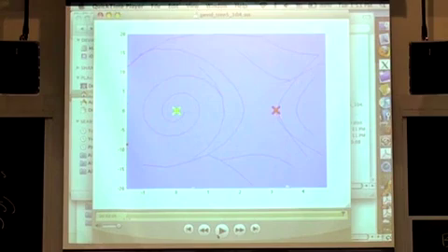There's a couple things you could try, and actually I recommended to Mike earlier today that he should do this for his final project, the case with the actuator limits. You can imagine making a soft limit, some sigmoidal limit, and having the gradients of that visible from your linearization point. Or you could imagine the LQR design that does both the quadratic cost and the bang-bang simultaneously. Haven't done it yet, but I think that's consistent.